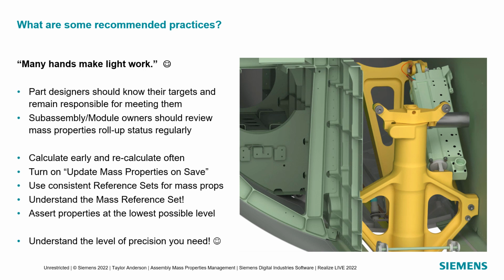That expressions partition is a little heavier piece of the part file that's not loaded as part of things like minimal loading. And so minimally loaded assemblies load very quickly, of course, super quickly. And that's great, and you can do a lot of mass property work with assemblies minimally loaded.